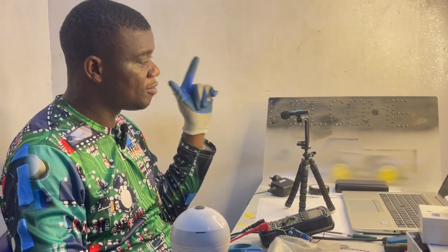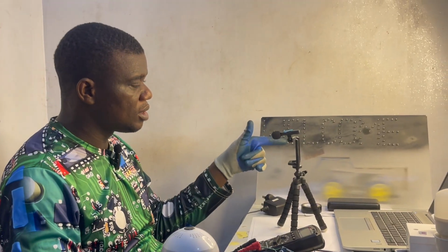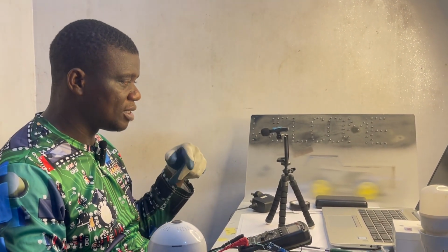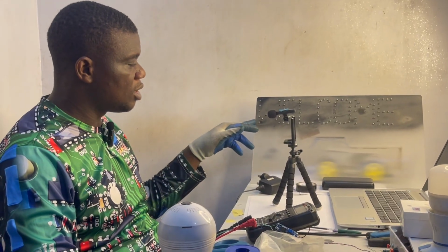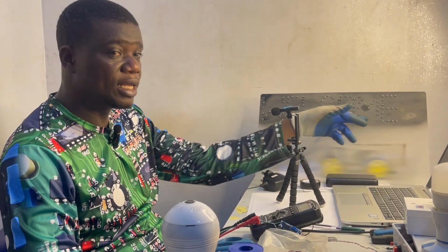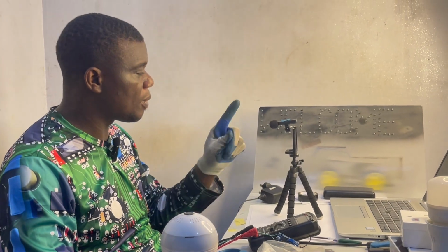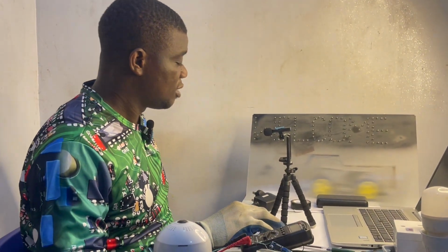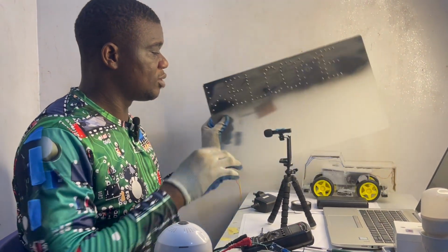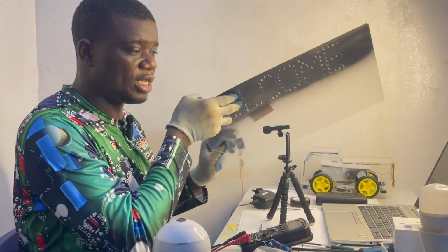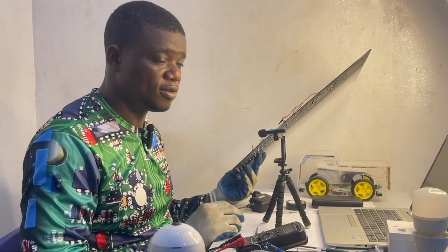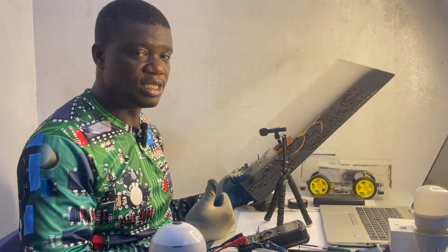But in those 14 wires, because I want to use a timer to drive it, what I did, I took all the cathodes together and brought out just one wire, where you now limit with just a resistor before you ground it to the common ground. So after that, you have to join all the anodes too, but they are not going to VCC straight, because if you do that, you won't have the feature we are trying to add with the IC.